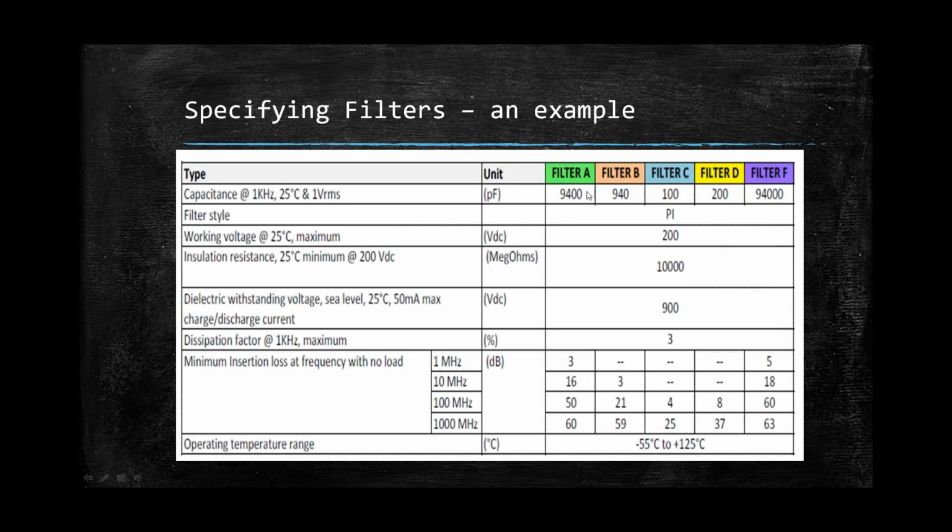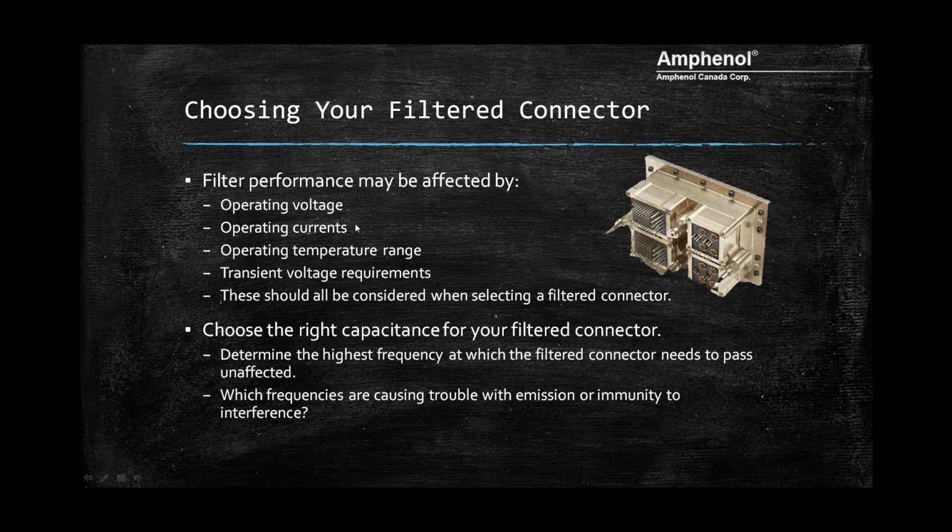And again, here's the advantage of the Amphenol Canada system. When that connector was returned to us, what we did was remove the springs from those 2 locations. We applied a conformal coat to the inside of the hole so that the pins were a feed through, and it worked great for the customer. So we were able to repair that quite cost effectively for the customer, rather than having a solder design where you basically have to probably throw away the whole system. So that was an advantage.